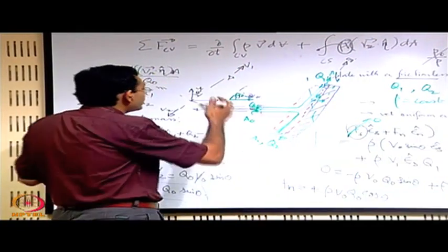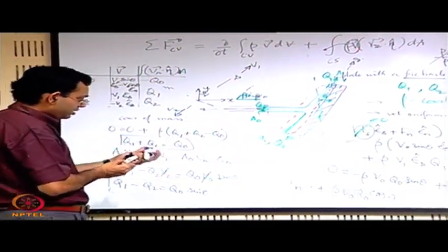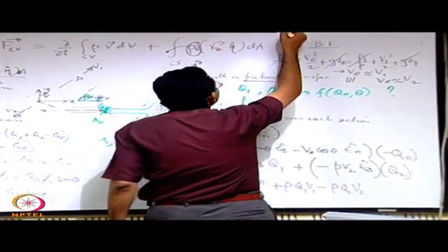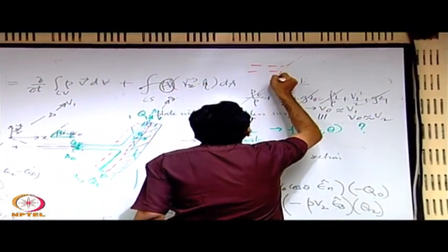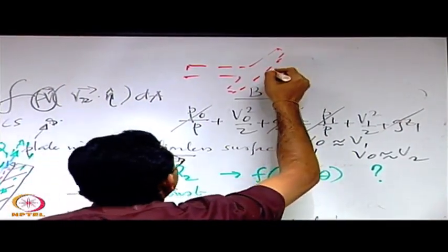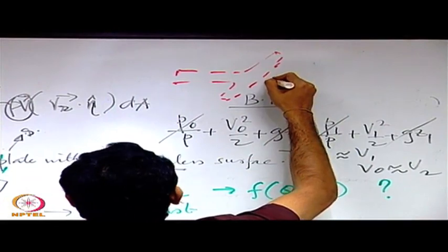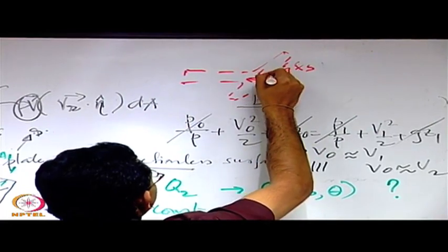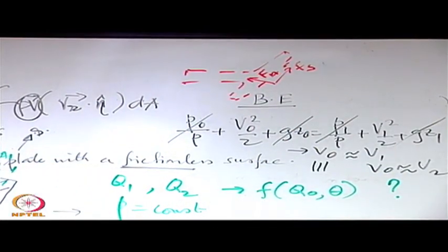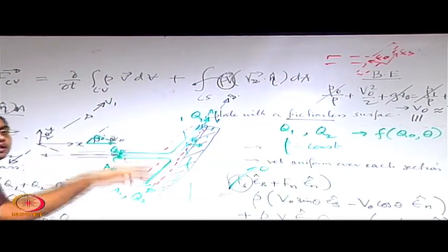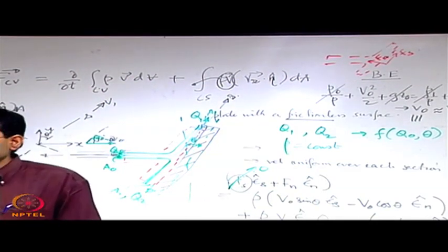So if you had drawn a free body diagram of the control volume, then what would have been the forces acting on that control volume that you would have shown in the free body diagram? Let us say that this could be your control volume. So you could have a force in the tangential direction Fs and normal direction Fn. Assume that the same thing is occurring almost in a horizontal plane, so the weight you are not considering in this plane, not that weight is not there, but in this plane of forces weight is not important.